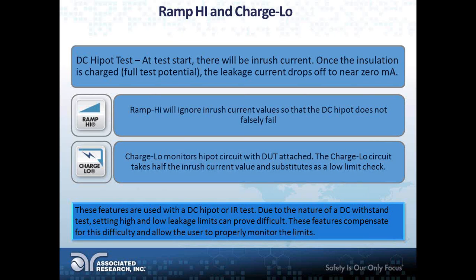Other last few things. I know we're almost at the end of our one hour allotted period of time, but there are a couple more things that I want to throw out there. I know we've already talked in quite a bit of detail about AC versus DC Hipot tests, and today's webinar was mostly based on AC, because the 500 VA requirement comes for an AC Hipot test only.